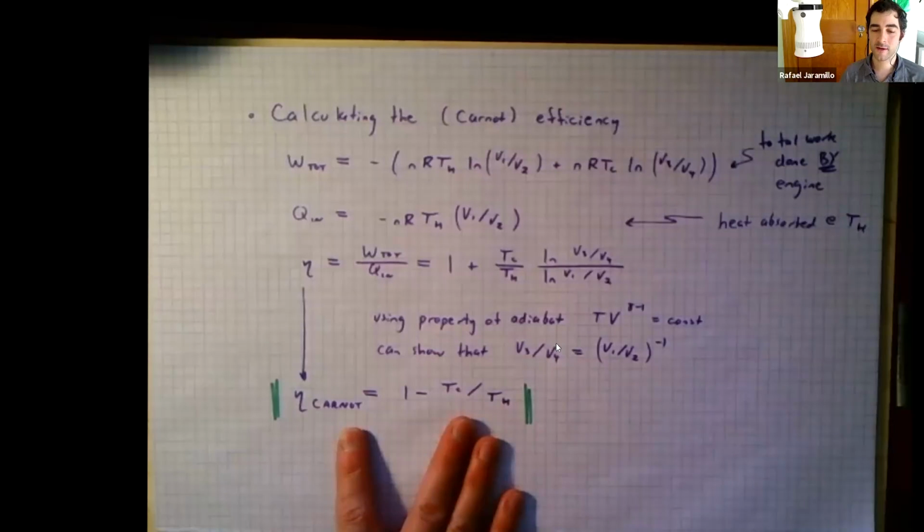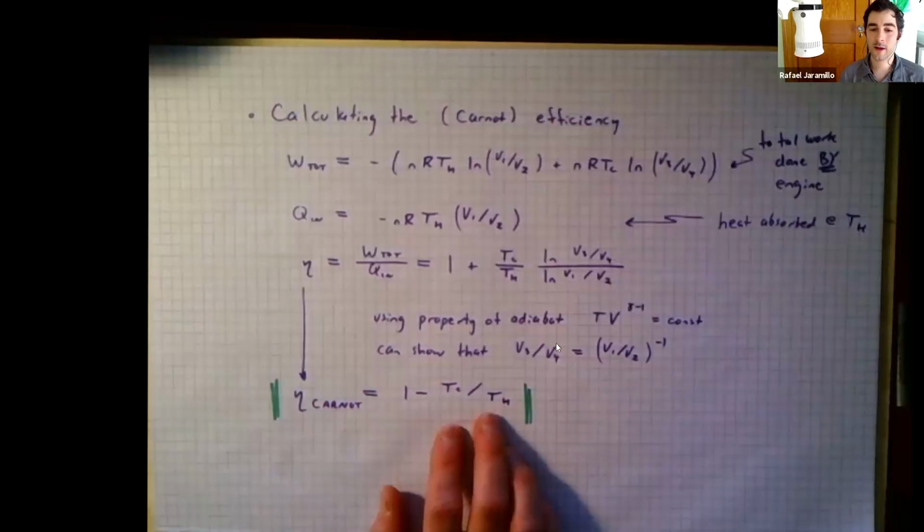Increasing T hot, for example, you could do by using supercritical water in your working cycle, allowing you to burn your fuel at a higher temperature. There's a lot of material innovation that's needed in order to enable that, because you're increasing the high temperature part of the system. And we know that you need really advanced alloys and ceramics and thermal barrier layers and such to do that.